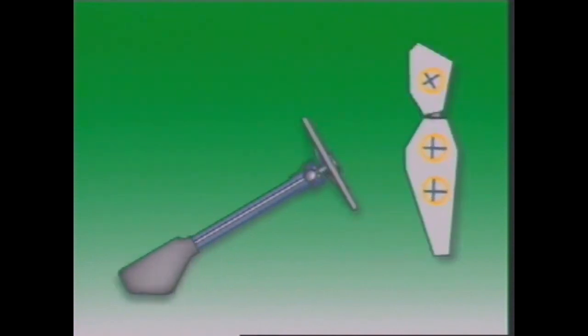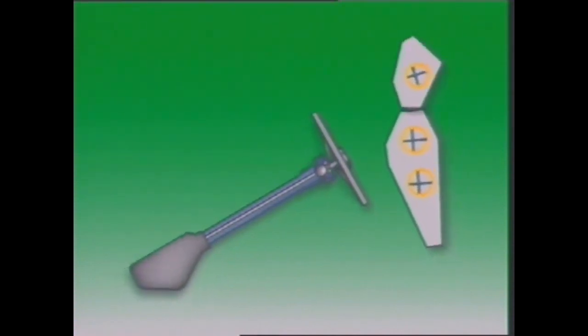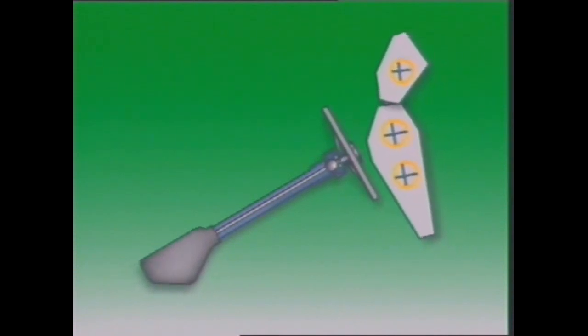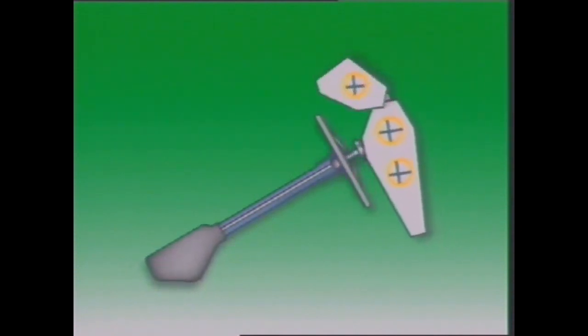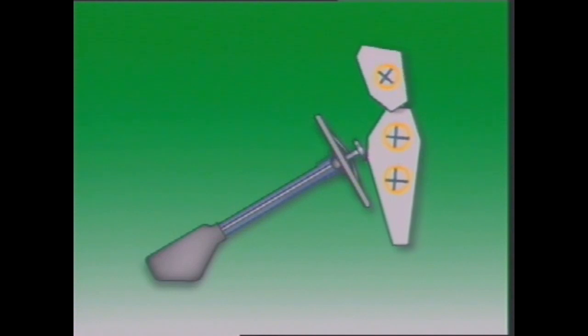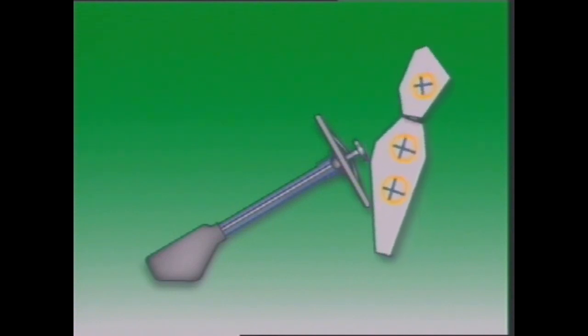In many frontal collisions, however, this caused serious injury to the driver, partly because it was forced back towards the driver's head, and partly because the sudden stop forced the driver onto the wheel. To reduce this hazard, some steering columns are fitted with collapsible sections that protect the driver.